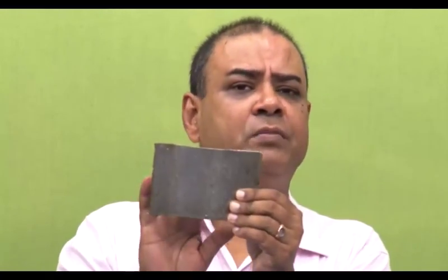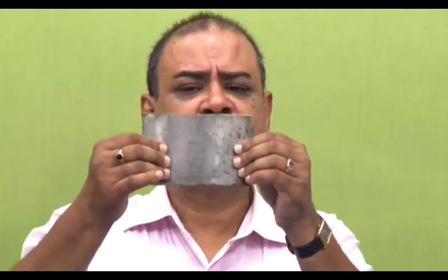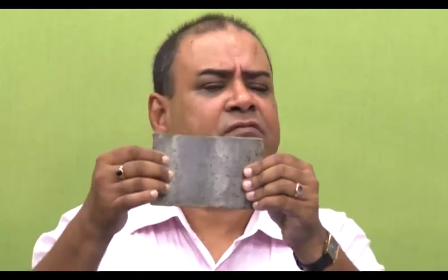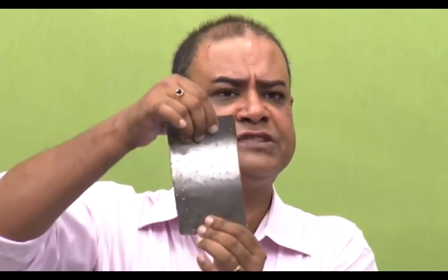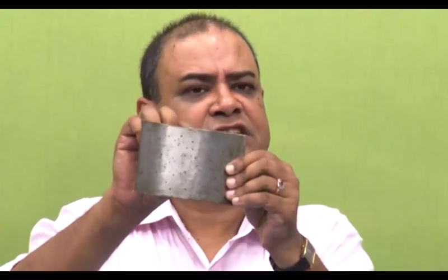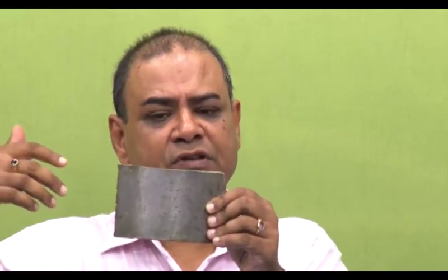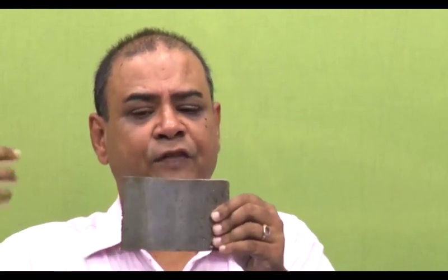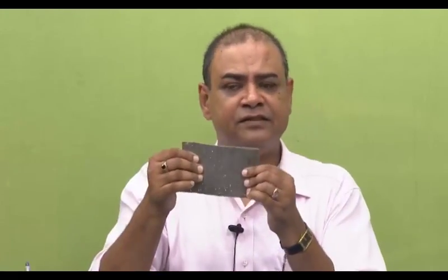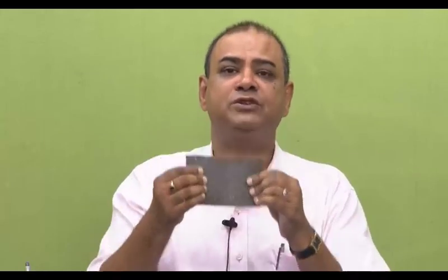So, I am just talking about a structure made of some material like this, and these structures are designed to hold some load. Now, once we have holes like this, the cross section is decreasing. The design load will be felt heavily on these smaller cross sections, and then the stress would go beyond the yield point, it will start yielding, and the situation may arise that it will crumble into pieces.